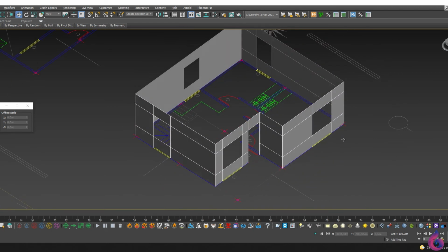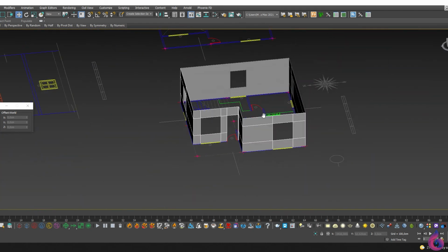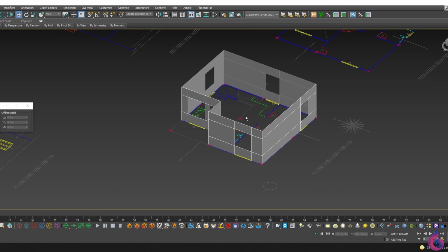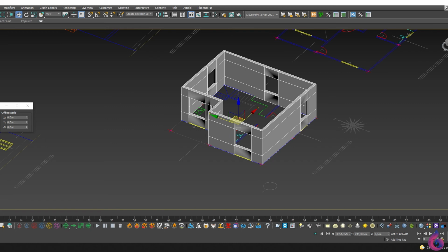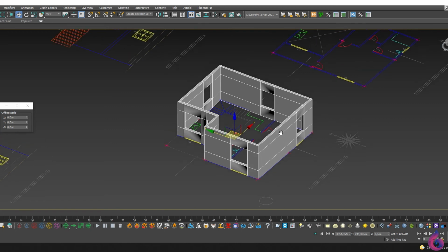As you can see, the angles are not right. To change this we choose Straighten Corners. Here are some minor defects, which we will fix by selecting the entire site and from polygon smoothing group select clear all. If this does not fix the problem, we will convert to editable poly again.